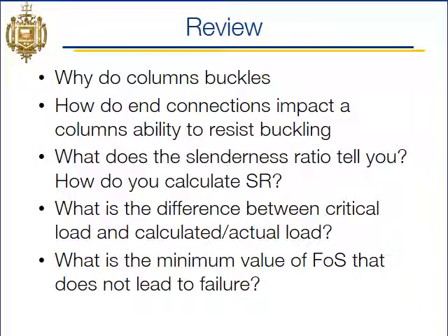All right, and here is the review. So why do columns buckle? From axial loads that cause column instability. How do end connections impact a column's ability to resist buckling? So by changing the end connections, you can vastly change the strength of a column, right? Because that changes the effective length, and we know that lower effective lengths make for stronger columns.